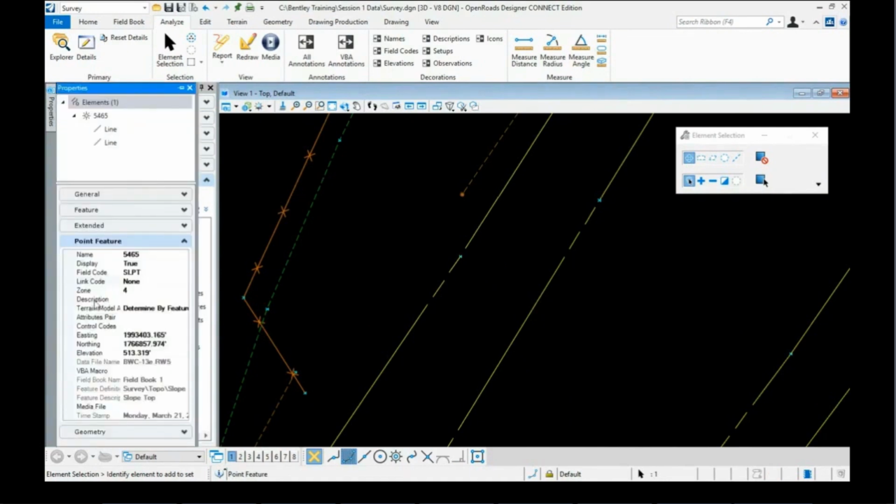The point is selected, and I'm going to choose Properties on that. And right now, I'm going to edit down here in the control codes. These control codes are things like joining points, if I'm doing any templates, like curb and gutter, standard templates kind of thing. If I'm doing some of my taping, rectangular taping codes, those are going to be here in the control code.